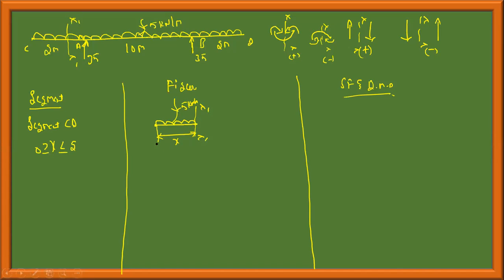Okay, I have not taken R into consideration. You should look at this. So I can write this as total effective load, 5 into x acting at this point. Now shear force F is equal to summation of vertical forces, which is F equal to minus 5 into x, since this is acting downwards. F at x equal to 0 is 0. F at x equal to 2 is minus 10.